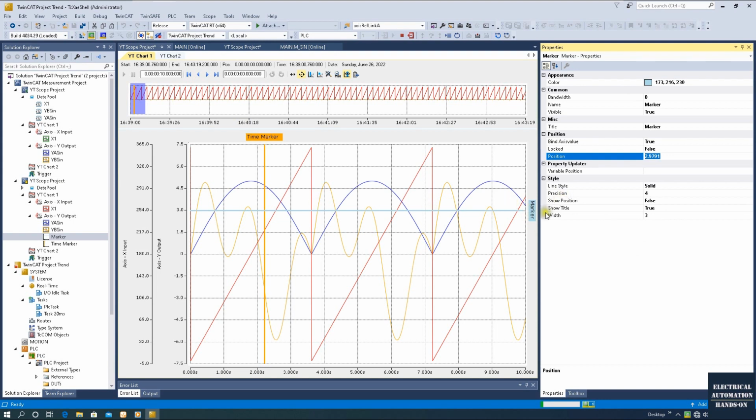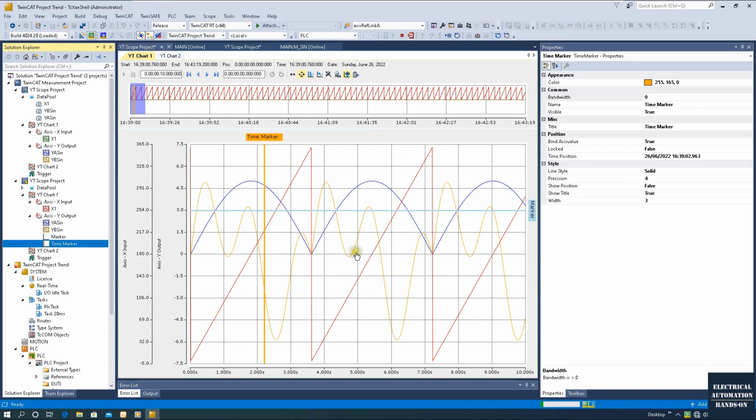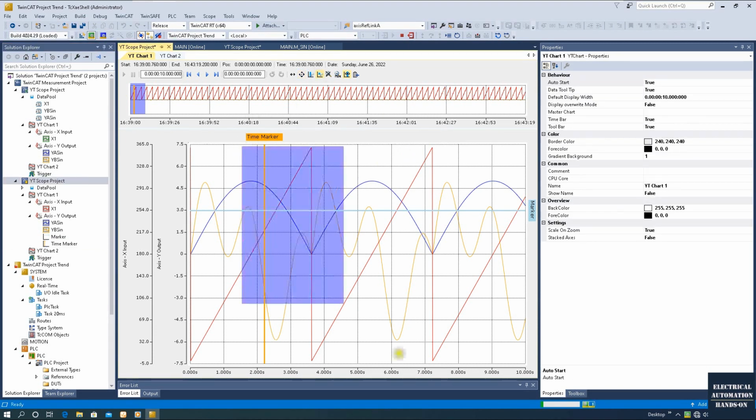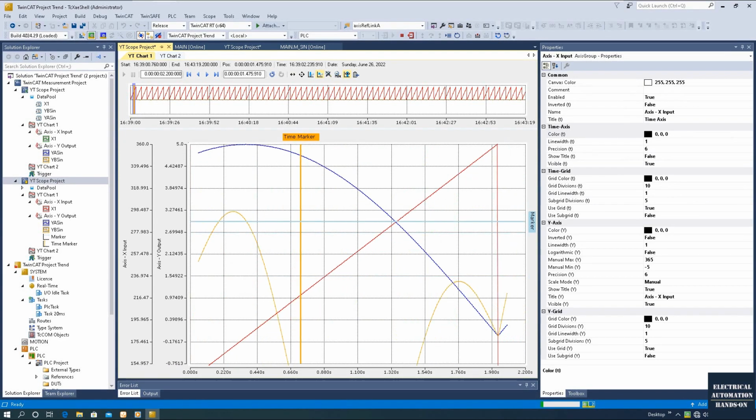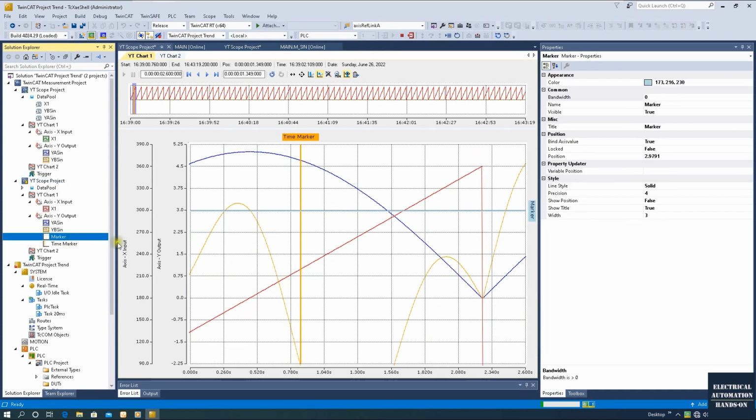And we can change to a different color. We can create multiple markers, especially when we compare the time from here to here, right? In some cases we want to compare the period within these 3 seconds, what the values were. So we can create 2 time markers here, and you can calculate and compare, or you can zoom in and compare some detail in that short period. So in that short period, what the 3 values were, right? Using the time marker is also very convenient.